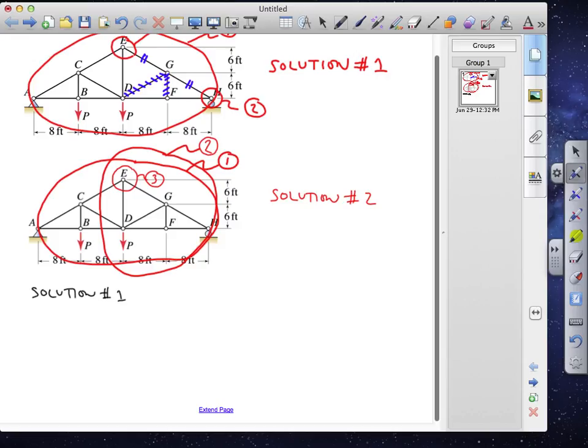Our first free body diagram is of the whole truss. As with our previous problems, there's no reason for us to sketch the details internal to the enveloping surface. So we'll just represent the reactions and the external loads.